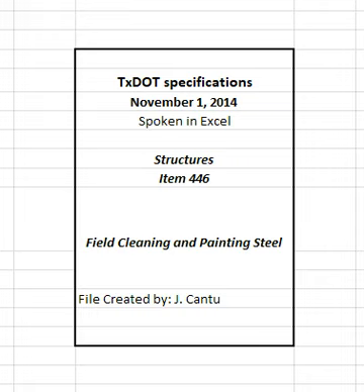Overlapping seams and entryways, and exhaust air filtration system capable of creating negative pressure inside the enclosure, causing the sides of the containment to have a concave appearance and demonstrating minimum 100 feet per minute cross-draft airflow and minimum 50 feet per minute downdraft airflow in all areas within the containment. In place of a full containment structure, a modified containment system may be proposed for the following situations.